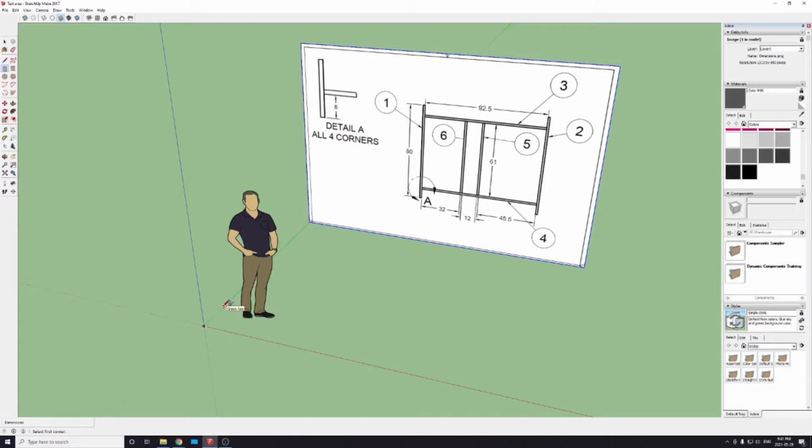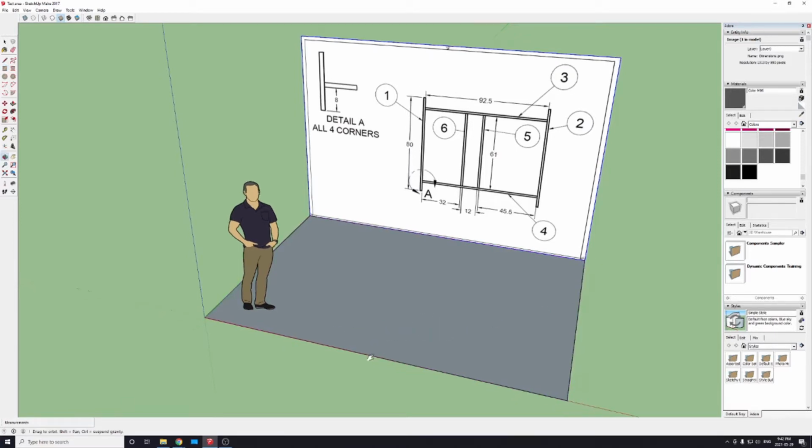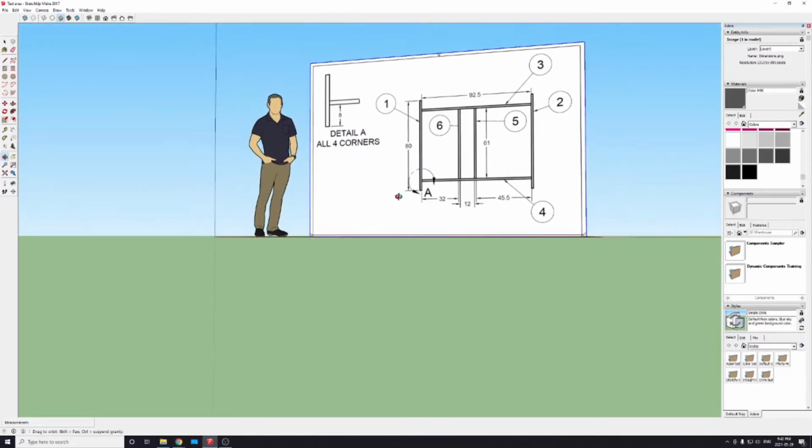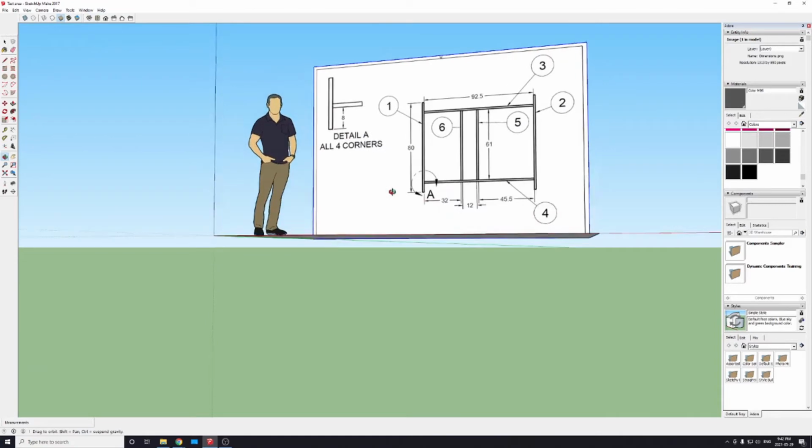So we've got our rectangle selected. We'll start at our origin again, left click once, and we'll just drag it out here somewhere, doesn't matter. And let's just actually index to that drawing there. Okay, so now we have a paper thin wall. If we look on the edge of here, it basically has no thickness to it. That in itself can sometimes cause problems.